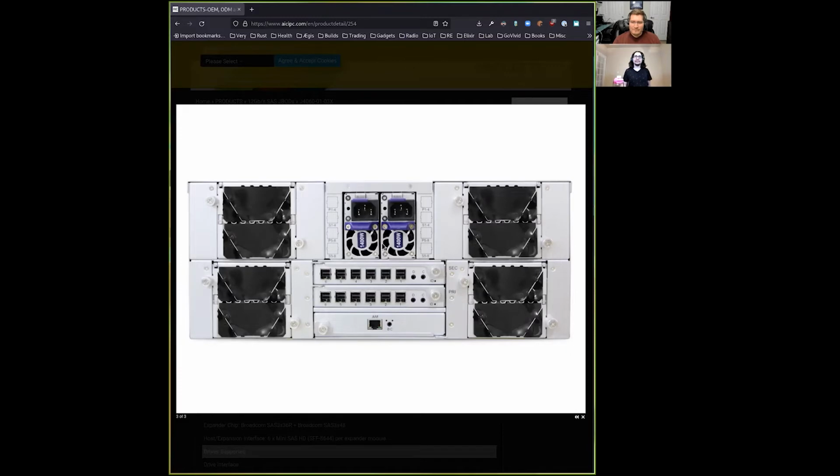So you'll definitely need a different sort of outlet for that with more amperage. Meaning you need the 20 amp power connectors with the slanted prong rather than the standard 15 amp connectors. Exactly. And these are right here below that. Can you guys see my cursor? Yeah. Oh, yeah, okay, it showed up. Cool.